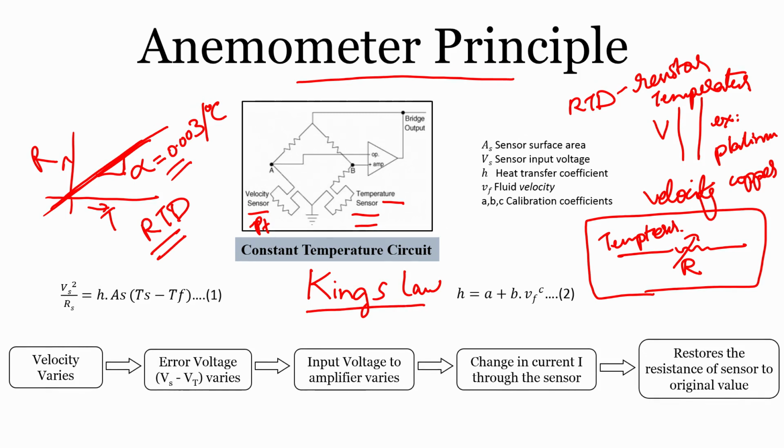The derivation is in the next slide. So, I am just showing how the sensor can be integrated in a bridge circuit like this, and you can force it to operate at constant temperature.